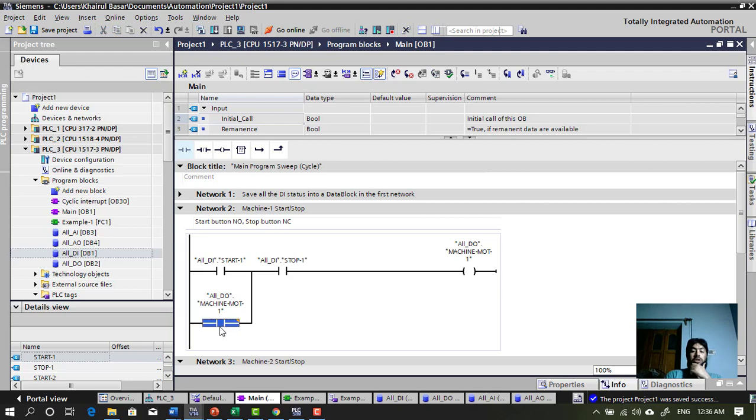This instruction has a bit that was already turned on in the first scan when the operator pressed the button, and we are executing this in the second scan. So when the operator releases the switch or push button, this output will be on through this parallel network.